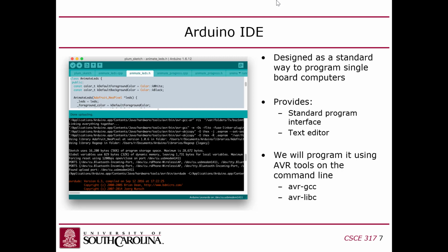because you have to be careful with which libraries are included. I had an experience where I was using the Intel Galileo, and I was doing this IR controller. Everyone says, oh, IR is really easy to do on Arduino. You just download the IR library and write a few lines of code and you can do IR, infrared, right? So I did that and it didn't work, and I found out later it was because the library was built with all of the hardware-specific features of the Atmel, and it didn't support the Galileo. In fact, none of the Arduino libraries supported the Galileo. So they advertised it as working, but if you're doing anything with any kind of I/O, the code that you wrote in this IDE didn't work on the Galileo.